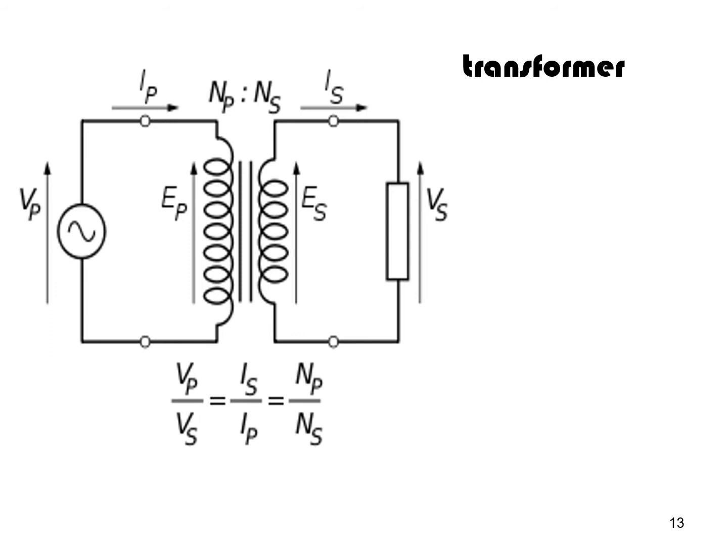The electromagnet is changing because the current on the incoming side is alternating current, or AC, and is switched back and forth from positive to negative. So the magnet is switched back and forth from north to south. The ratio of the incoming voltage to the outgoing voltage is the same as the ratio of the number of incoming coils to the outgoing coils. The purpose of the transformer is to convert voltage.